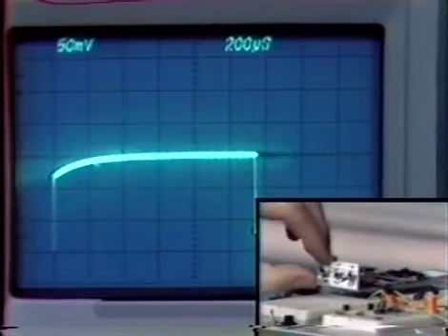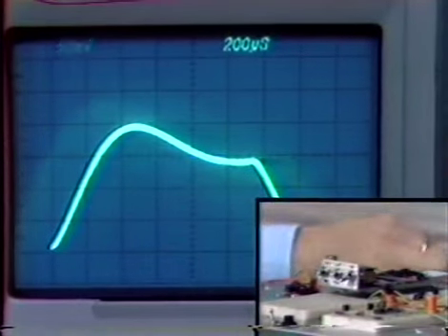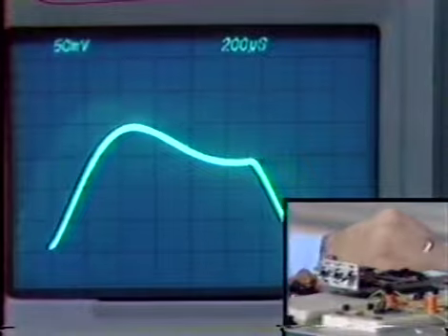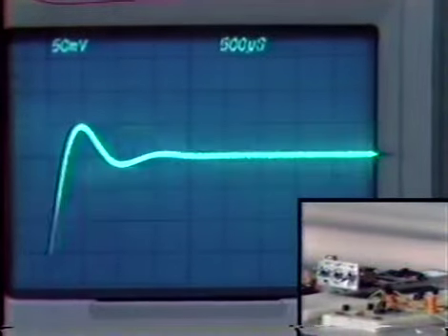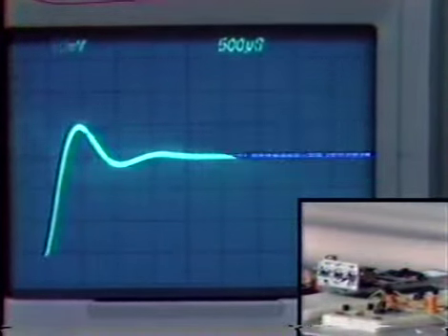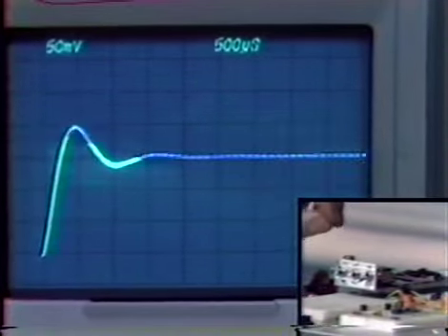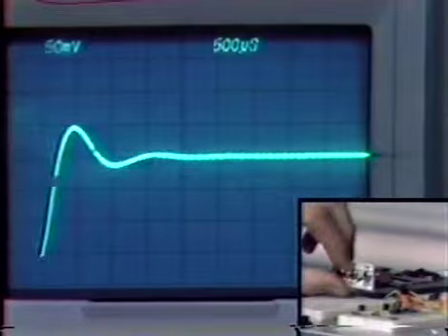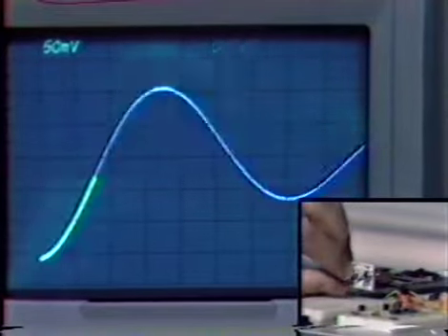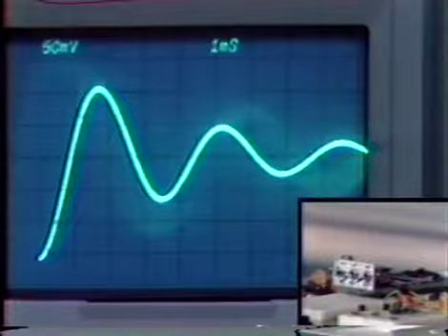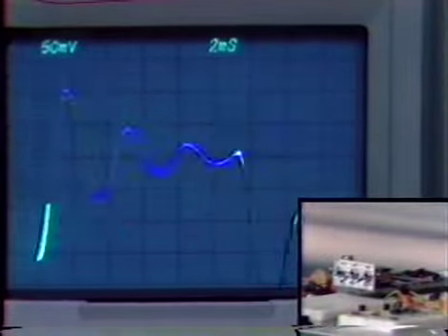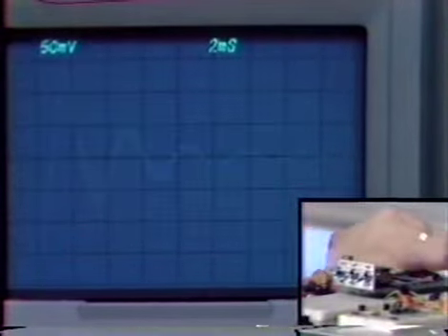Here's 1 kilohertz. Have to slow things down. Again, relative to the pole location at 10 kilohertz, we have poorer stability. At 100 hertz, considerably poorer stability once again. And beyond this, we begin to lose things quite dramatically.